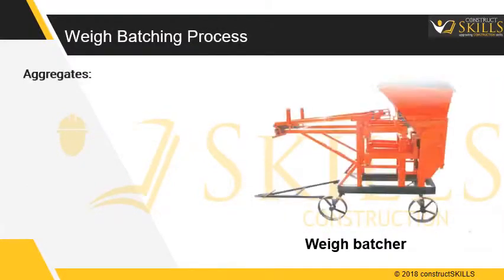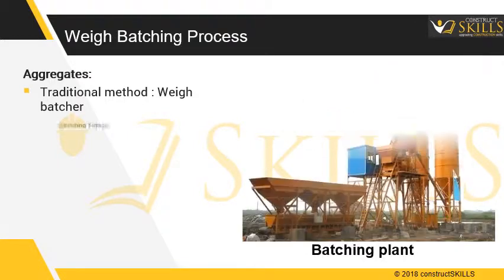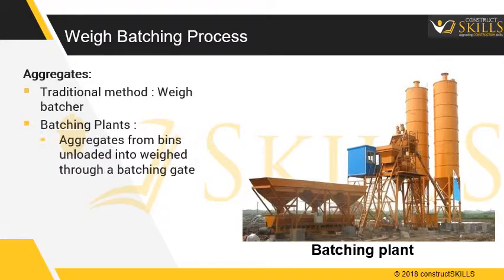Aggregates weigh batching. In 3-bag mixer machines, bins have load cells, and aggregates are added manually in the bins. In batching plants, aggregates from bins are unloaded pneumatically into the weigher below, through a batching gate. The required amount is then conveyed to the concrete mixer.